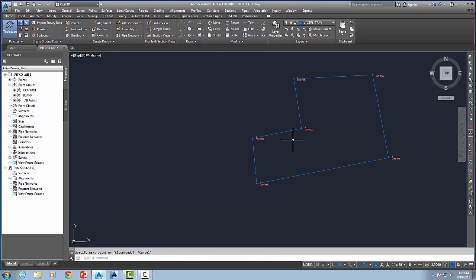So the way this would work is, I'm going to delete these out real quick. Let's say we wanted to put in an arc here, a 3-point arc, utilizing these 3 points. If I went into the normal arc command, I could just type in A for arc, which gives me a 3-point arc, and it wants to know a start point. What I can do at this point is go over here, grab the point object, select that point object, that point object, and that point object. And what I've done is turned that normal AutoCAD command, that is normally looking for an OSNAP or some other kind of input, northing and easting or XY, into one that works conveniently with points. So we can see that this is going to be a real enhancement.